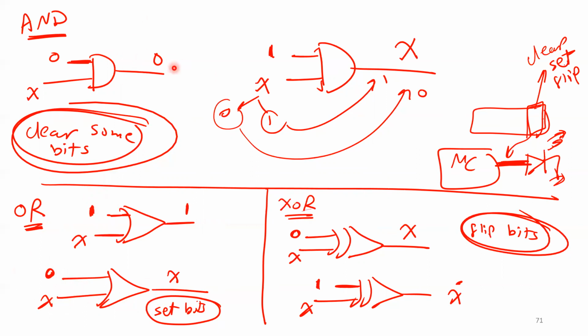Here, I know it's a little bit confusing because I'm going to use a different way here. Look, but if you understand this way, you're not going to be confused. Here, 0, here 0, don't change. Here 1, don't change. So if you don't want to change some bits here, you have to use 1. Okay, if you want to clear, you have to put 0 here. Here, don't change. So 0 means 0. Okay, 1 means you set.